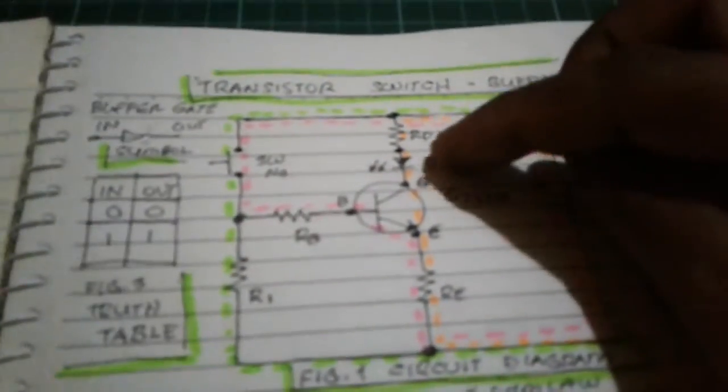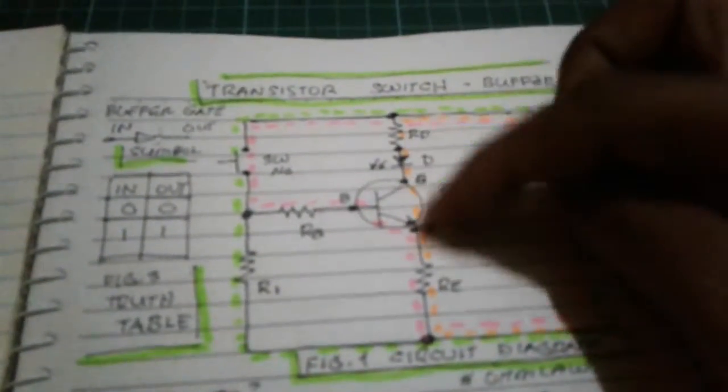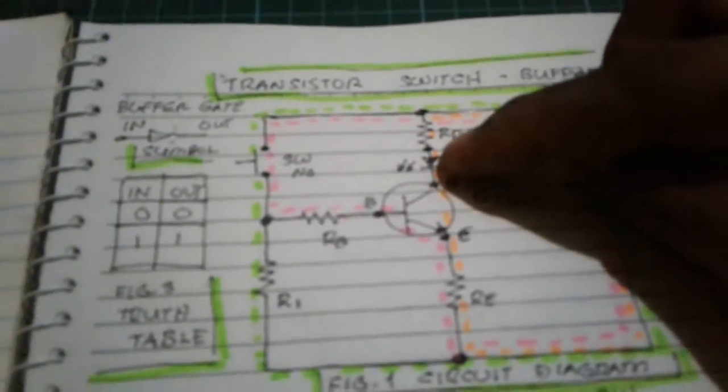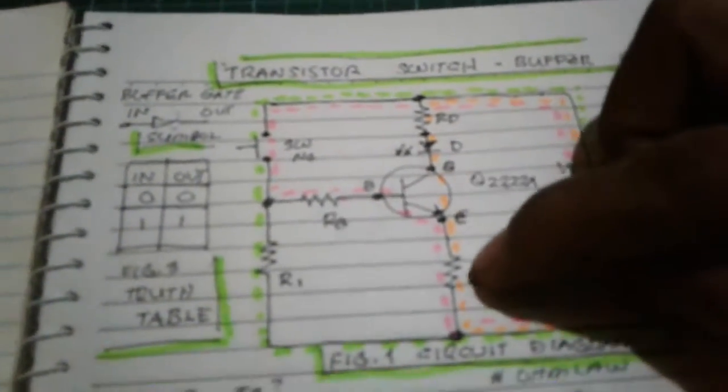And then we have here VRD plus VRE is 2.7 volts. The voltage drop across these two resistors is 2.7 volts. Using voltage divider, I just divided by 2. And now we get 1.35 volts each, since they are equal. So the sum of all the voltages here is equal to 5 volts.